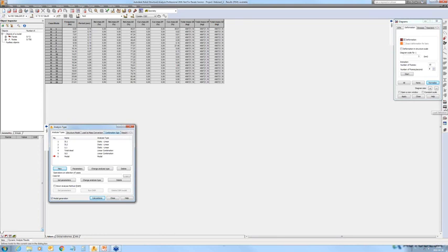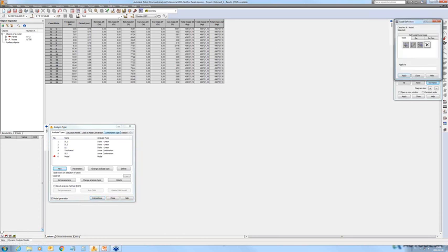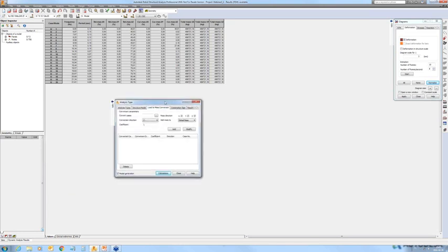I mentioned that by default, the mass in the mass matrix is the self-weight of the structure for modal analysis, but it is also possible to define both nodal or bar, uniformly distributed masses. Of course, as the masses usually correspond to applied loads, we have the option to convert the defined load into masses.